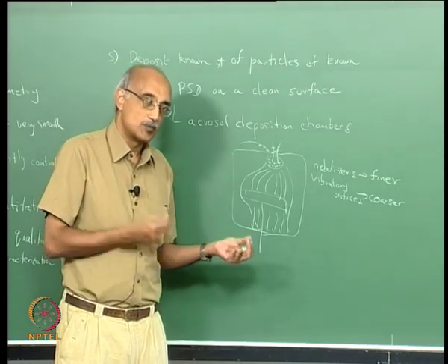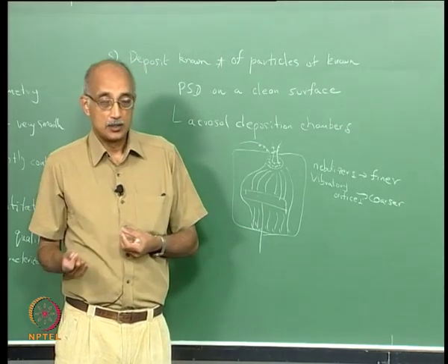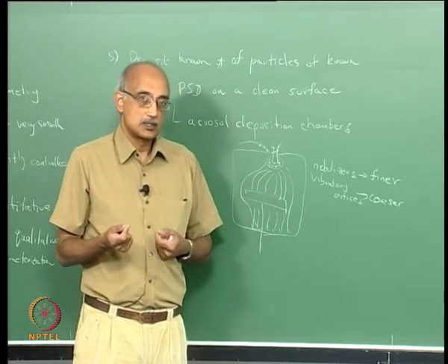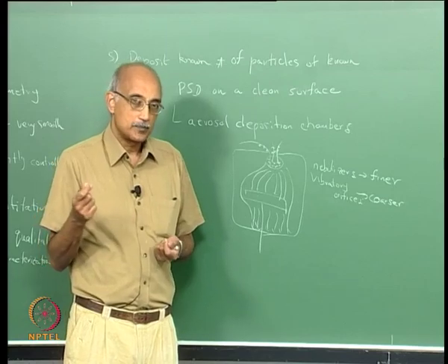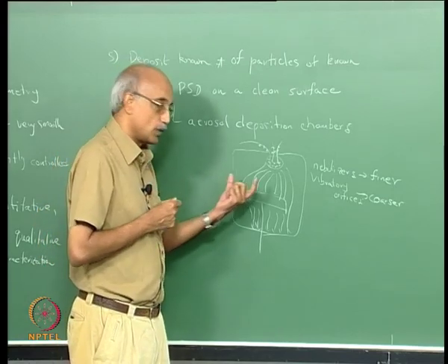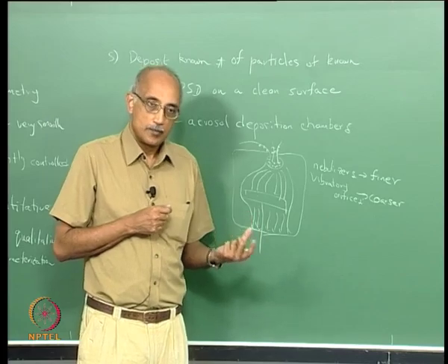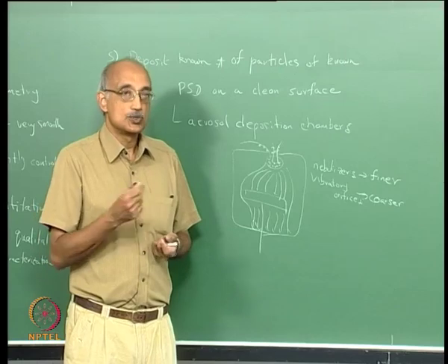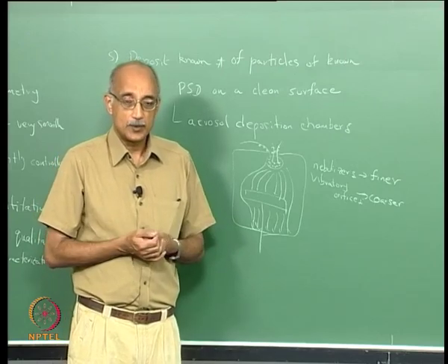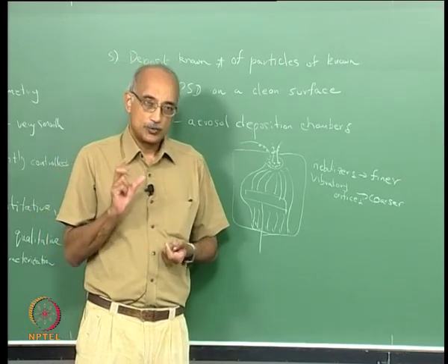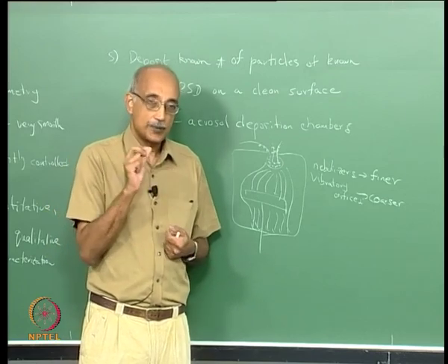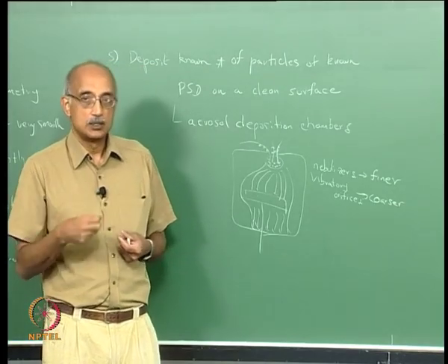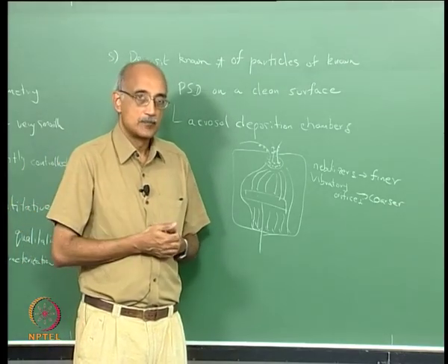But for particles that are smaller than 0.1 microns or larger than 1 micron, simply relying on flow streamlines is not sufficient. So, you have to control not only the flow streamlines in those cases, but anything in the design of the chamber that can affect diffusional paths. For example, when you talk about diffusion, even slight temperature non-uniformities can be sufficient to cause significant thermal diffusion to set in.